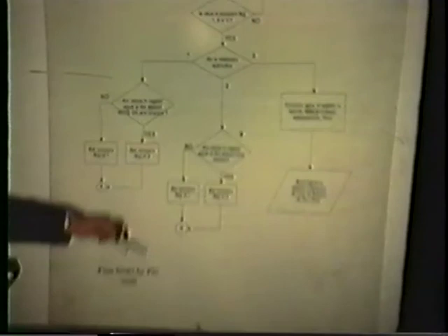Here's the block diagram of the PIC. At the beginning, the code simply reads 8 bits of data. This part of the code was pre-written and is available from Parallax. Once it has read the 8 bits, it then scans through the bits for the desired note on, channel number, and note value. These values have been hard-coded into the chip.